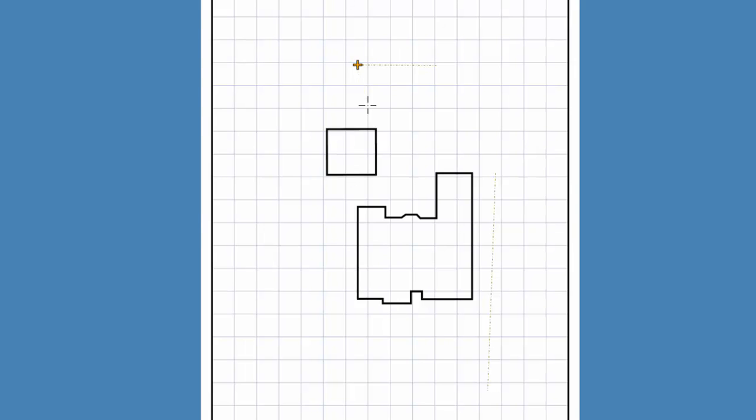I continue the process by selecting the line command again, press the A key, drag the mouse cursor near the back left corner of the house, and press the right mouse button to snap onto the house. Press the left arrow button and enter a distance of 26.5 in the point polar command and press enter.